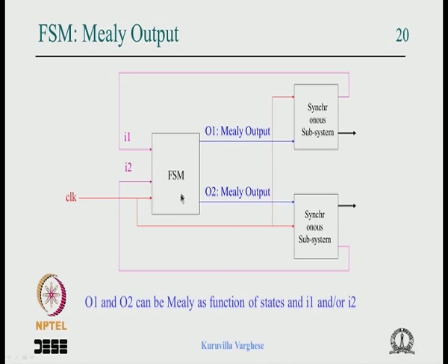The state machine and all these synchronous subsystems are working on the same clock. There is some output, we don't know what kind, maybe a counter or timer decoded output, going to the state machine input and so on. Let it be anything, it doesn't matter. This output is synchronous to this clock and goes to the state machine.